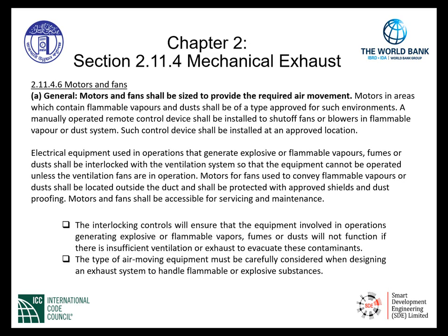Motors or fans used to convey flammable vapors or dust shall be located outside the duct and shall be protected with approved shields and dust proofing. Finally, motors and fans shall be accessible for servicing and maintenance.